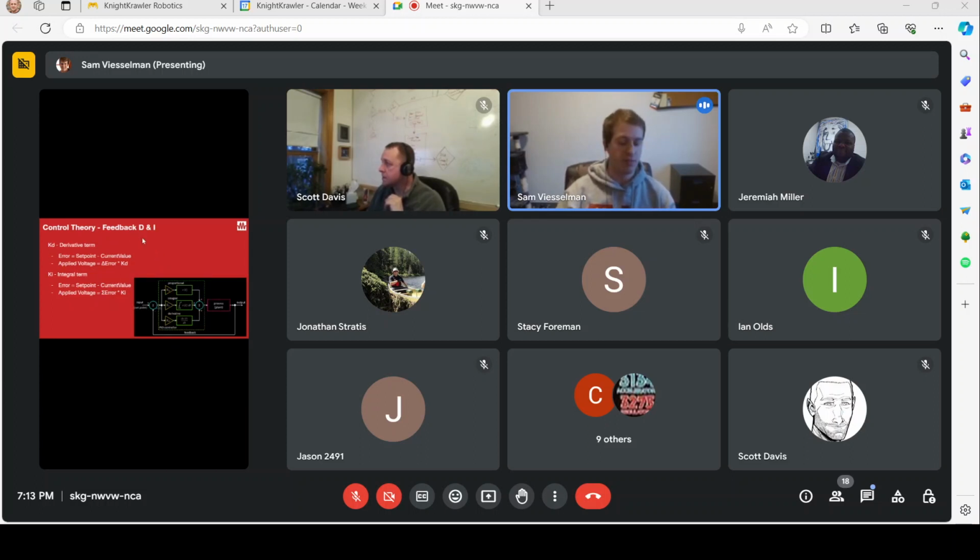The other two terms are the I and the D. I suppose I split the order here, but they're the derivative term and the integral term. What Kd is doing is very similar, where we're finding the error in the same way, the gap between our output and what we want it to be. But in the case of derivative, it's saying what's the change in error, and applying voltage based on the change in error. If our error is rapidly changing, Kd is going to apply a lot of voltage to try to cancel that.